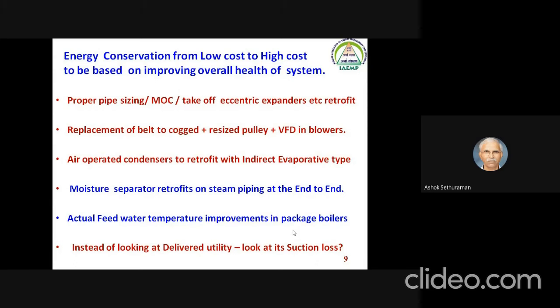in that. We have suggested to many industries, 10,000s of boilers are working in this textile processing region where we are working during the audits. Having fitted the moisture separators at the boiler end and at the heavy equipment end where indirect heating is required, they could achieve their productivity. Thermal productivity went up, their steam consumption also dropped, their fuel consumption dropped drastically, more than 10%.